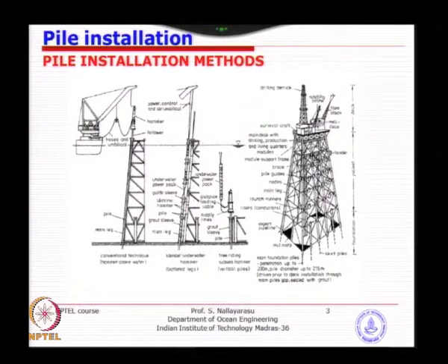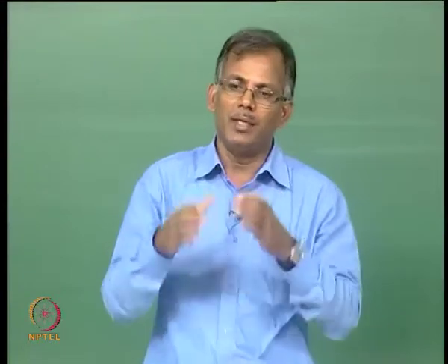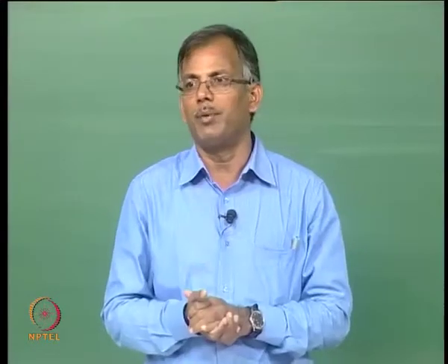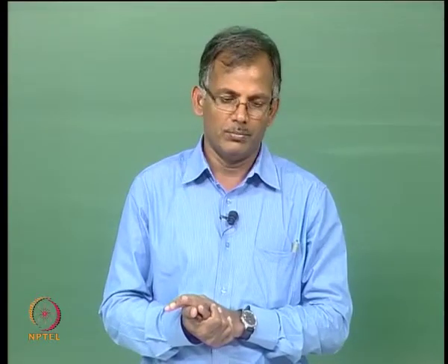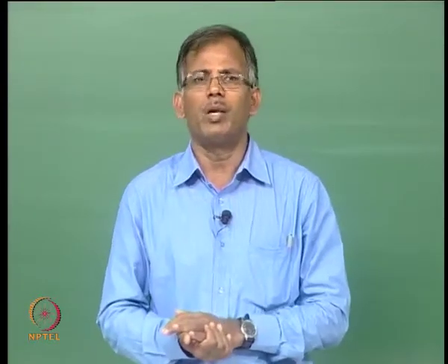Typically, if you see this picture, the main pile is put through the annulus, or the hollow portion of the leg, and just inserted inside. You have already predetermined what should be the gap available between the pile and the leg. So, typically we give about 1.5 inch.